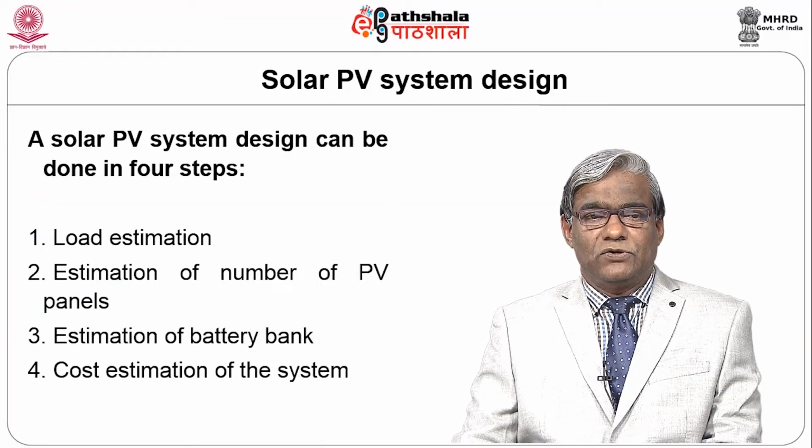A solar PV system design can be done in 4 steps. Number 1, load estimation. Number 2, estimation of number of PV panels. Number 3, estimation of battery bank. Number 4, cost estimation of the system.